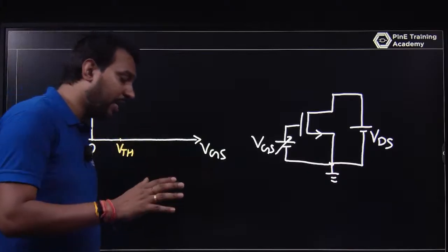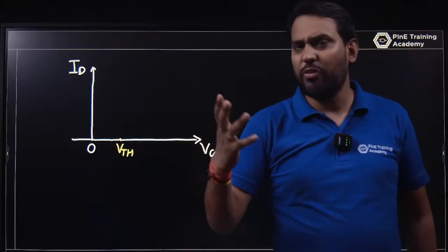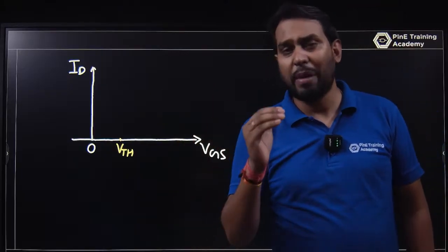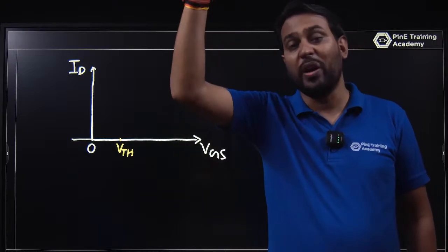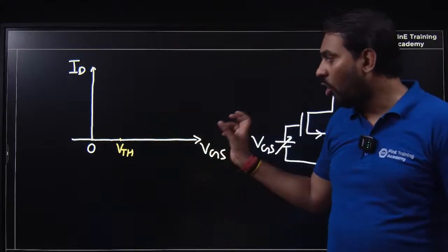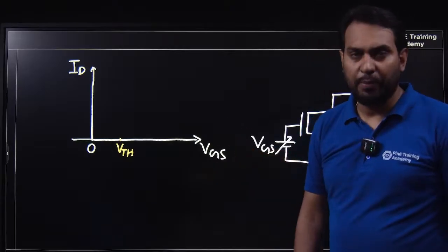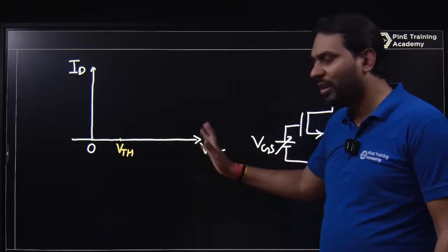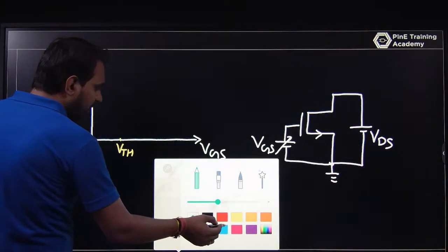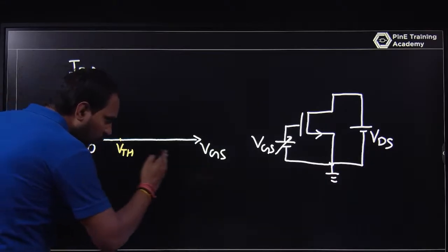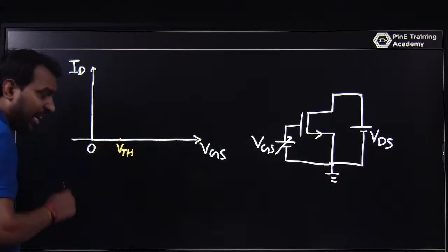Of course, you must have an understanding. If you are using GPDK 45 or GPDK 90 or TSMC of any technology node, you have a manual file. You have a nominal voltage. You can't use 5 volt or 10 volt or 20 volt. So there is a nominal voltage, which says how much voltage you can use. If you're talking about 45 nanometer technology, we can use up to 1.2 volt. So say you are sweeping 0 to 1.2 or 0 to some 1 volt. So before VTH, ideally